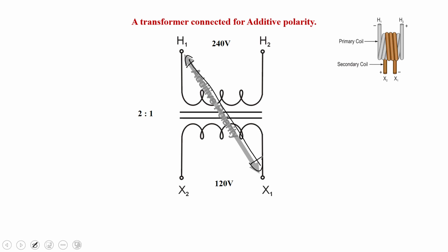Whether we have an additive or, what we'll look at next, a subtractive transformer, when we're just using a transformer by itself, it really doesn't matter too much. But when we start paralleling transformers and they have different instantaneous polarities, or we start connecting up single phase transformers in groups of 3 to make a 3-phase transformer, it becomes very important because we could cause a short circuit. So that's why this polarity is so important.